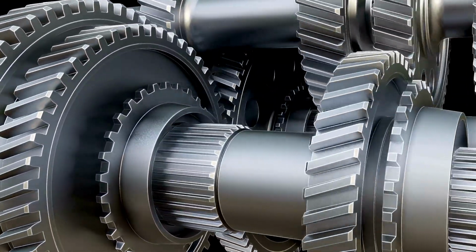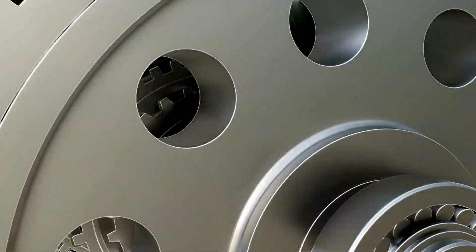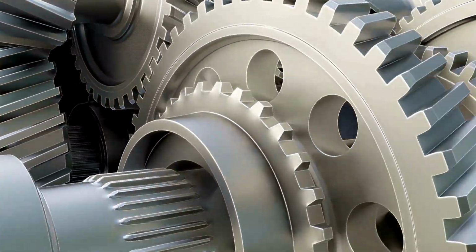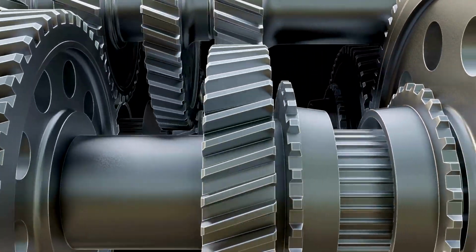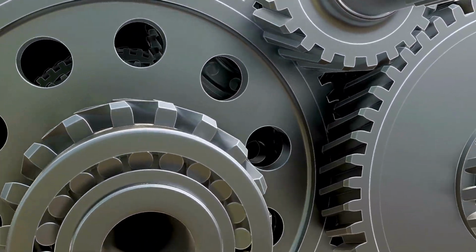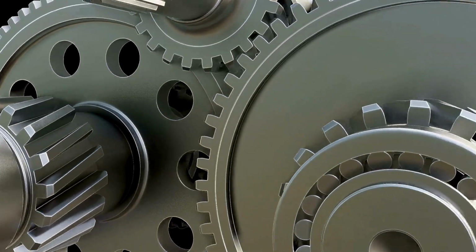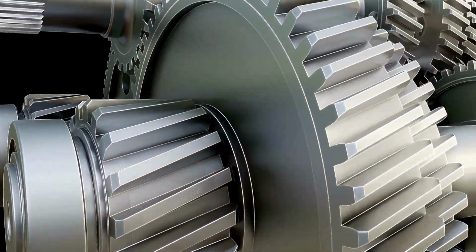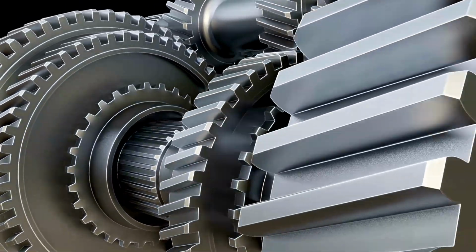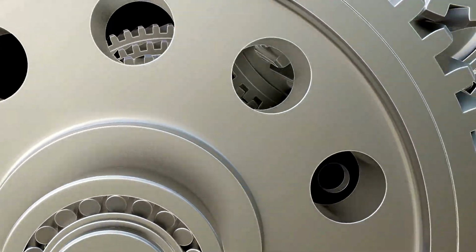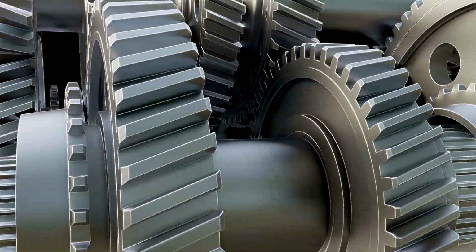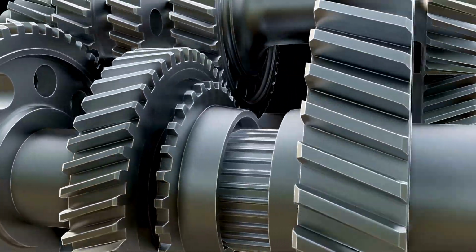Torque, a twisting force applied to a shaft, causing it to rotate. Shaft, a cylindrical member used to transmit power and rotational motion. Shear stress, internal stress within the shaft caused by the twisting force, highest at the outer surface and zero at the center. Angle of twist, the amount of rotation or twist experienced by the shaft under the applied torque. Torsional rigidity, a shaft's resistance to twisting, determined by its material properties and cross-sectional geometry. Polar moment of inertia, a geometric property of a shaft's cross-section that indicates its resistance to twisting.